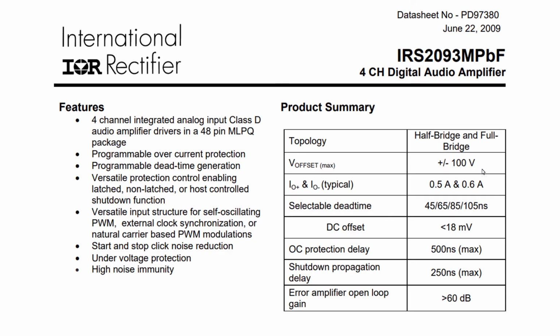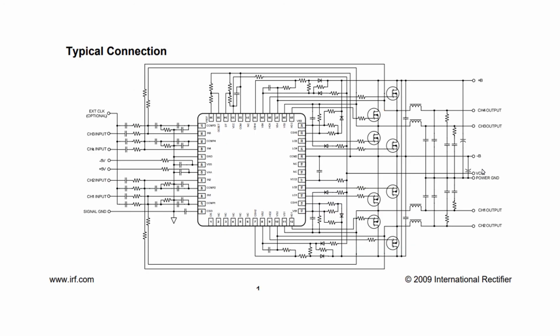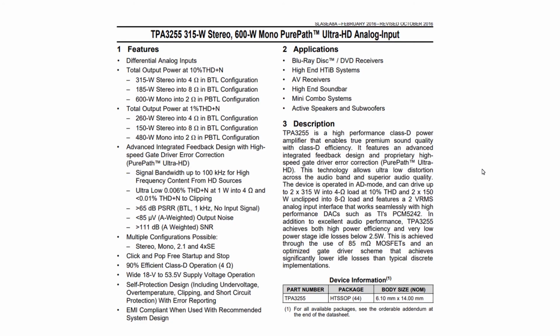Here is 4-channel gate driver, the same characteristics as for the stereo version. I haven't seen designs of this gate driver yet, but it may be a good design for 3-way speaker systems where 2 channels are connected in the bridge for a woofer and 2 channels in a single-ended connection for mid-range and tweeter. Why there are no such design in market? I think it's price consideration for a board. You can build a better design using 2 ICEpower 125A2 boards, separating woofer driver power supply from mid-range and tweeter board.